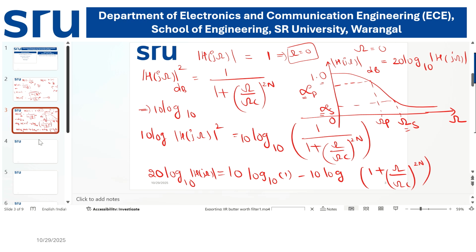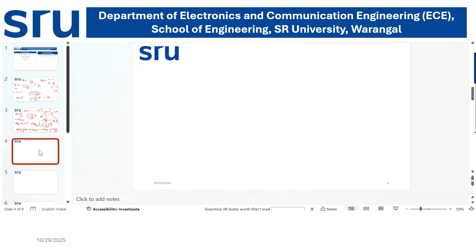Now log 1 value is 0, so the overall value is 20 log base 10 of the magnitude of H(j omega) equal to minus 10 log of 1 plus (omega by omega c) whole power 2n. Give it as equation number 2.